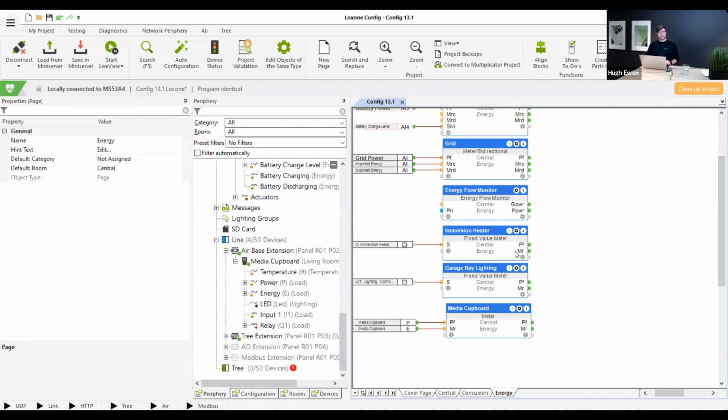Power readings from tree lighting is a very, very good one. Not at this point in time, maybe in the future. Will you have to start installing bigger SD cards? No, I don't believe so. I don't think there's any issue with the storage capability on the SD card. It's the read-write cycles. 8 GB is endless amounts of storage for simple data. It's the number of times we write to the SD card. And that's why the default statistics times are 30 and 60 minutes.